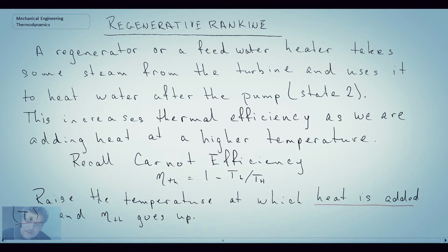And so that's essentially what we're doing. We're raising the temperature at which we're adding heat to the cycle, and consequently we will result in increased thermal efficiency. Now, in doing this, I refer to a thing called a feed water heater.